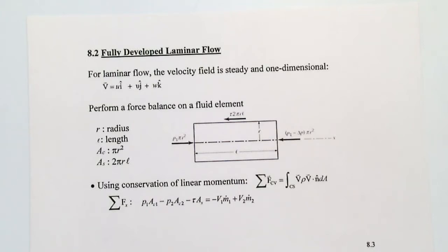Okay, if you assume you have a cooling system in a company, then only at the start of the pipe will you have that entrance region, but after that you will have fully developed laminar flow. That's why we only take care of the part that stays for the whole pipe system, except for maybe 1% or half a percent of the length of the pipe. That's why we are talking about fully developed laminar flow more than the rest.